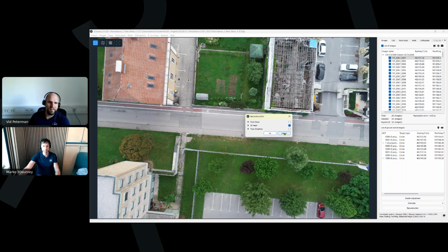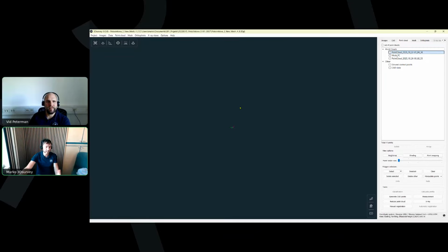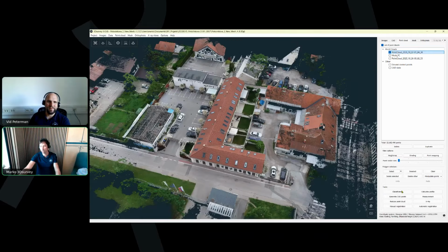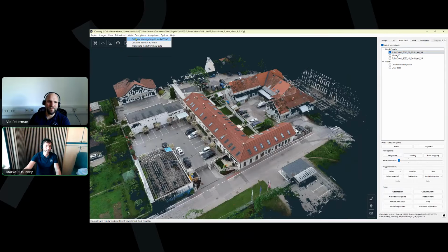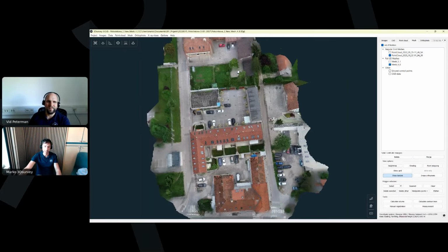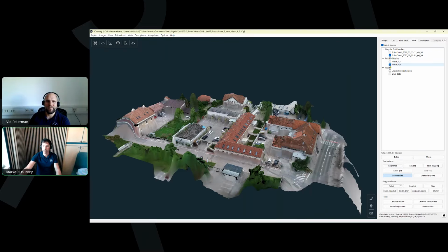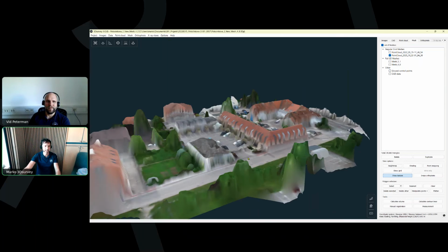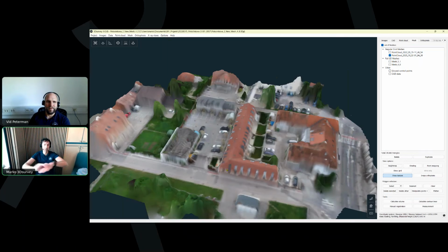When would you calculate the regular grid mesh, for example? So I would go and calculate the regular grid mesh in case I need volume calculations. Okay, yeah. So I turn on the point cloud. Of course, I would do the classification probably before, and then I go to the regular grid mesh calculation. Yeah, like that. But okay, this one is not classified, and now I get the regular grid mesh. I didn't classify it before. Okay, so definitely for volume calculation, or maybe if you need just a digital terrain model or something like that. Okay, yeah.